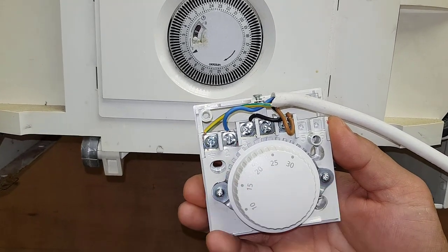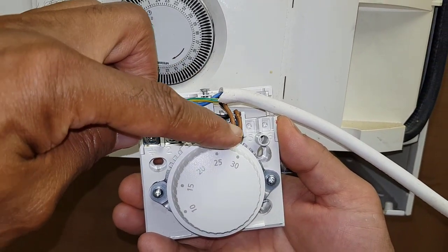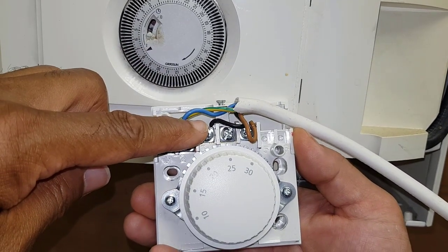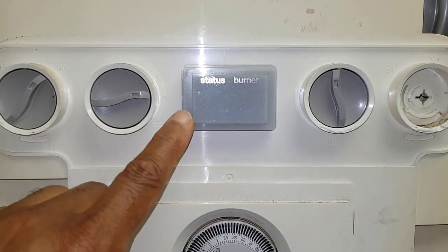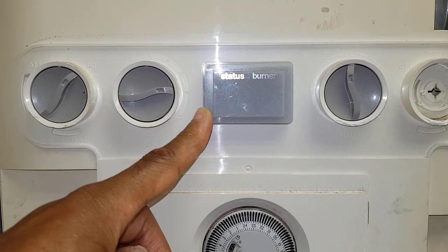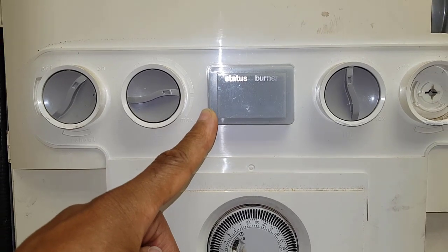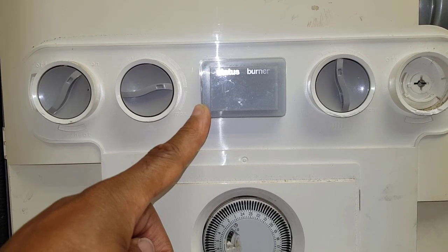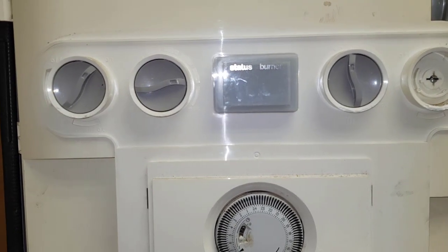You hear that click. Your feed would be coming in here and then going back out to the boiler and bringing on the C. That's then making a circuit, and then you've got your central heating demand. So that's what you get first. On your quadrant, you're making sure that is working. That's right.